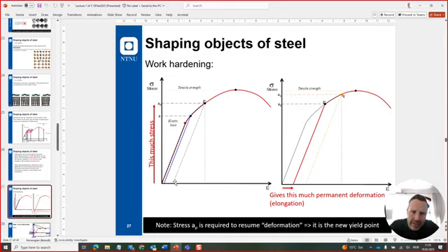If you now want to stress the specimen that has this permanent deformation, the graph now starts here at the red line. The red line should actually go all the way into the center of origo. And if we go straight up here, up until the point P, it will have the red graph here. The red graph should actually shift to the left. That is how the new steel would look. The new yield point is now P.